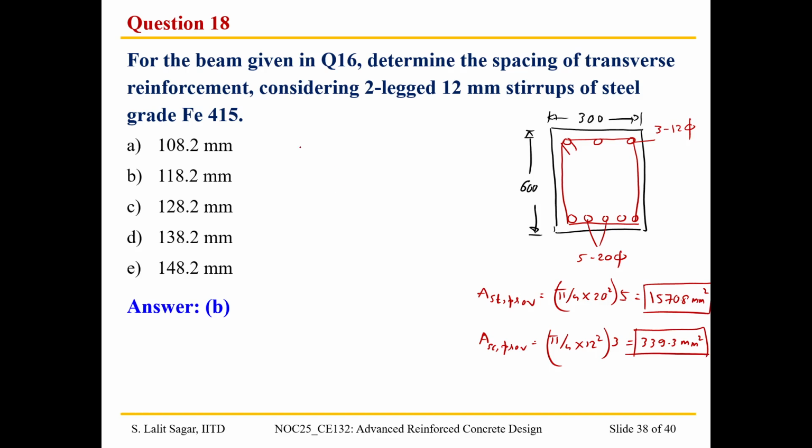Okay, so now let us proceed to design the shear reinforcement. We have already discussed this so many times, but still we'll proceed now. Vu equals VUC plus VUS, and VUC is equal to tau C into BD. Here tau C depends on PT and fck. By now I think it will be by heart, this concept would have been so clear since we have solved so many problems.